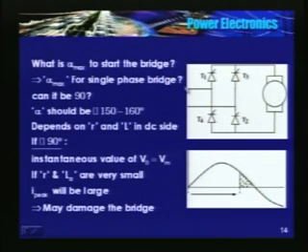It will so happen that a large current will flow and may damage these devices. So therefore, a safe value may be towards 150 to 160. It all depends on the parameters of the machine or the DC side. If I have an inductor, of course you can decrease this value. Otherwise, maybe start somewhere near this point and reduce alpha towards 90 degrees.